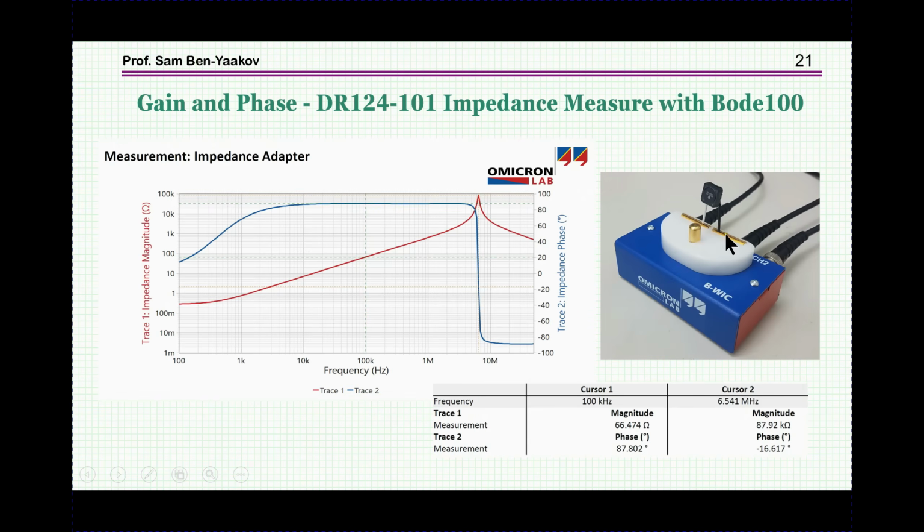And here we did this for the inductor. This is the Eaton inductor, and this is now the result for the impedance. The red curve is the impedance, and the blue one is the phase. Now the impedance starts fairly flat, because we are at the low frequency area in which we have resistive behavior, and then of course we have omega L. This is a log scale, so this is why it is a straight line.